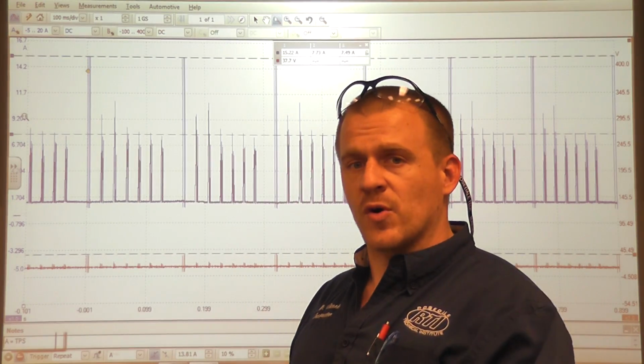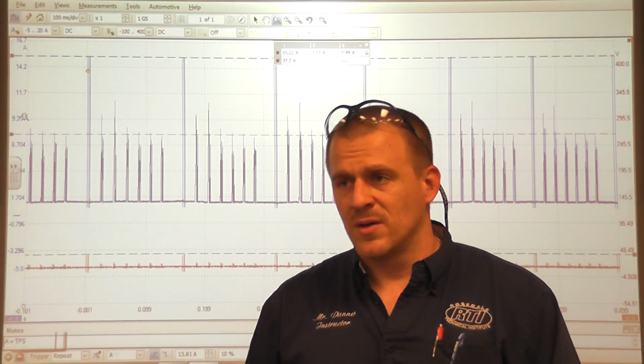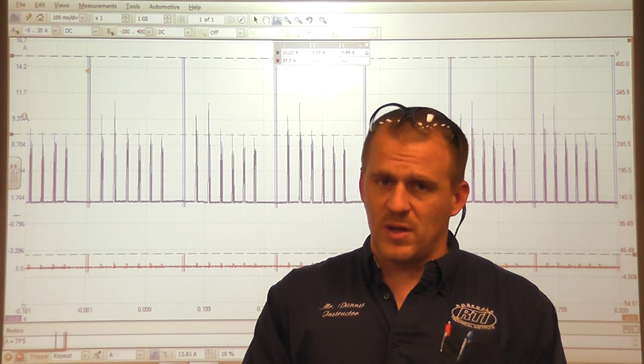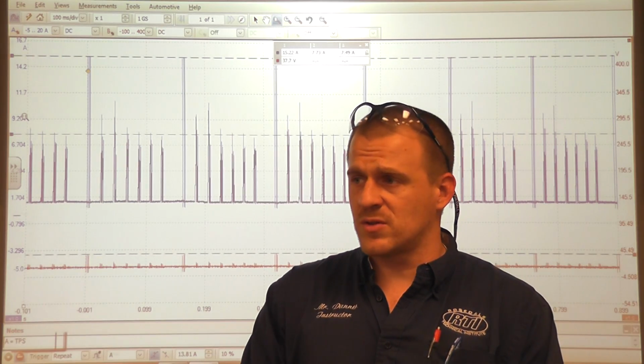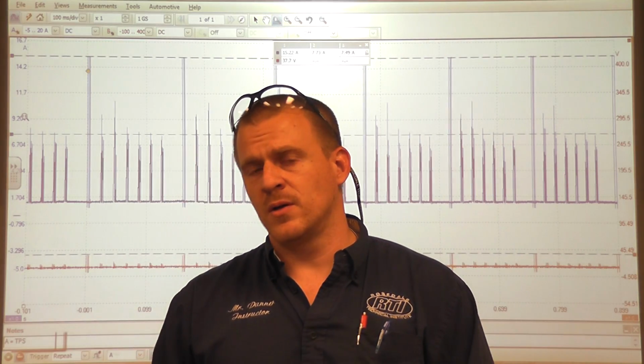We do have one other coil. We can go back and look at that part. You know, these are known for bad coils. I'm not saying we need to replace them all, but this is a good example of what you need to do. You have an output that fails and it cooks a driver. You better make sure you check that output. That's where we're at.